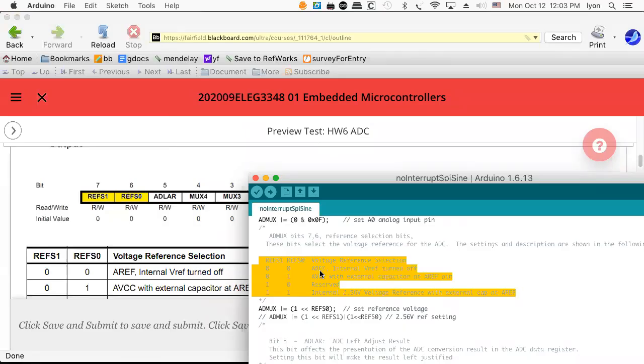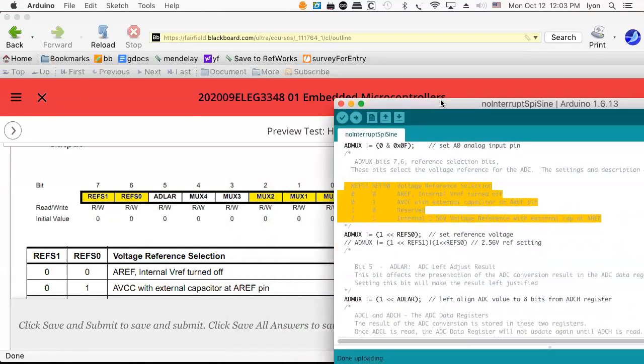If you said to me, I know that I'm going to be using my favorite guitar and its input is going to be exactly 0 to 1 volts, I could put in a 1 volt reference and that would be okay. And if you said, well, no, guitar outputs are low, it's going to be plus or minus 125 millivolts, which is probably closer to the actual output of a pickup, you could use a 250 millivolt reference externally and give it a precision reference and it'll use that for its ADC. So that's kind of a nice feature.